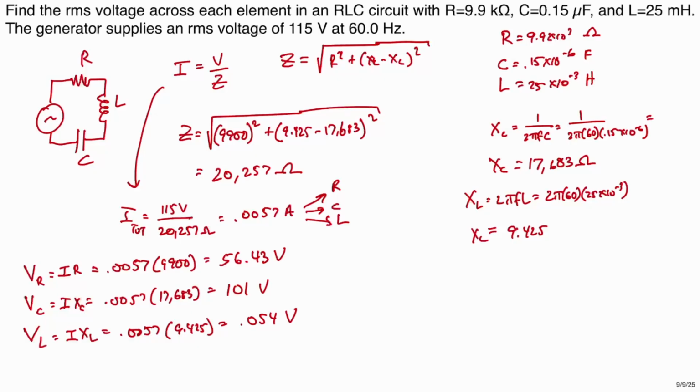If we add up all of these voltages, we get a number that's bigger than the voltage of the power supply to begin with, right? So either we just broke conservation of energy and the universe is going to implode, or something else is going on here. It's option B, by the way. So these are RMS values, right? These are like average values. Remember the simulation I showed you?